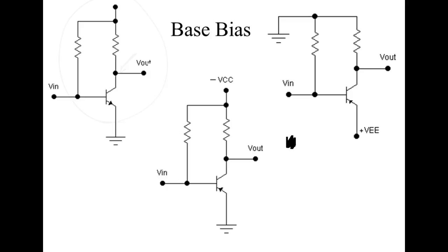So I come over here and I say, okay, I want this resistor to drop 3 volts. I would calculate the collector current, then divide it by the typical beta of the transistor. Then I would subtract 7/10 of a volt, and I would size that base resistor to do that. Then I choose the standard value and play around with it, right? And that's transistor design.